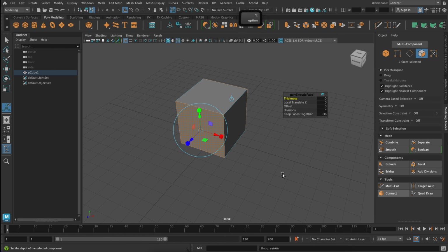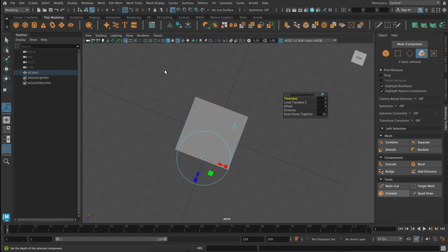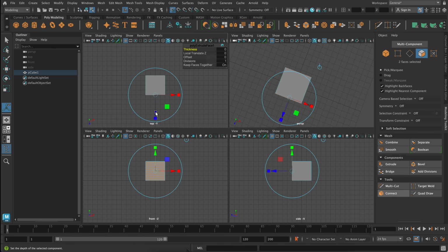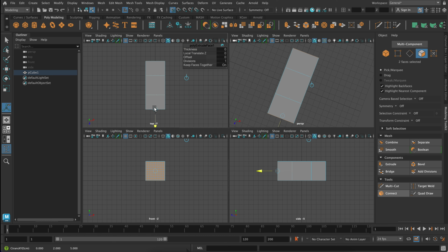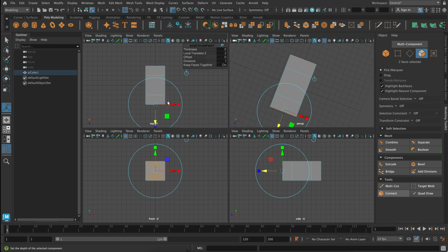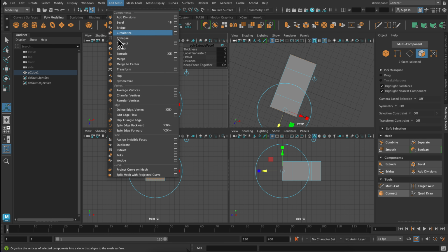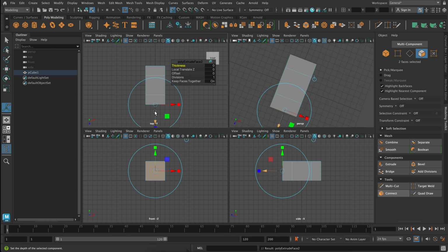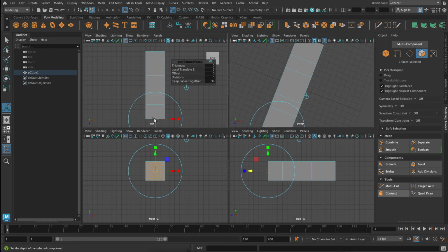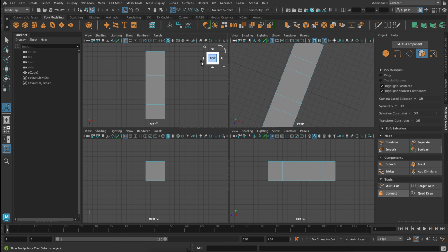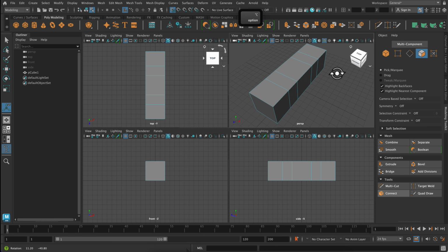And actually extrude. So I'm going to go to the top view, I think. And I'm going to use my grid snap and just snap to two grid places. I'm going to extrude one more time. So Edit Mesh, Extrude. And this time I'm going to do 3 grid places. There you go. So this is making the top of my E.